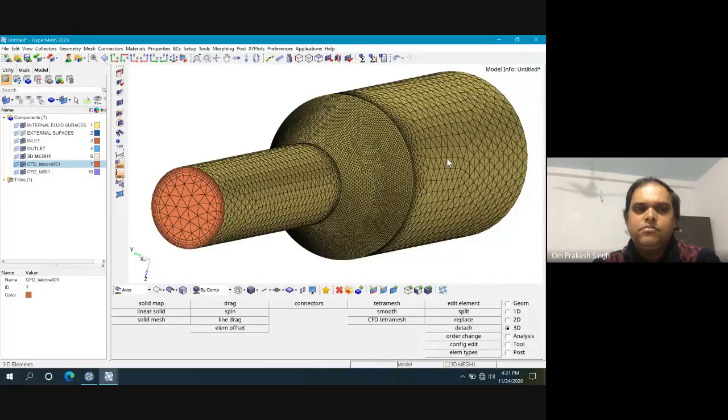But you have to do it. It doesn't matter where you do it. You may use OpenFOAM or Fluent or any software. This is the basic principle which one should follow to get an accurate result. I have seen many publications where it is done without a proper mesh, but that is not the professional way to do CFD.